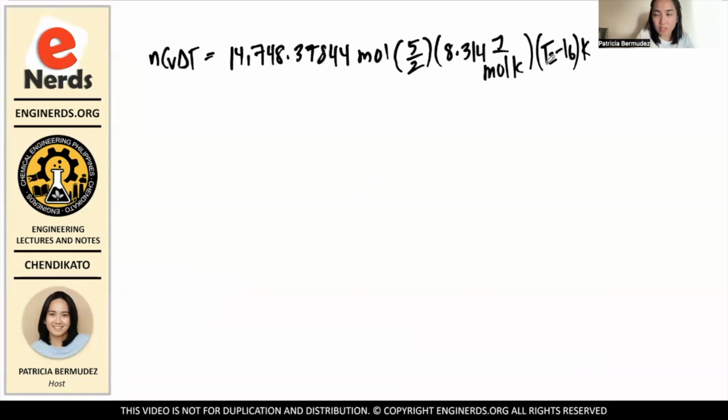So here we have injected T2, which is our final goal to find in this problem. And we know that this is Q, and Q is equal to 1,250 kilocalories. But we have to make the units consistent here. This one is in kilocalories, but that one is in joules, since moles cancel off and Kelvin cancels off, so joules remain.